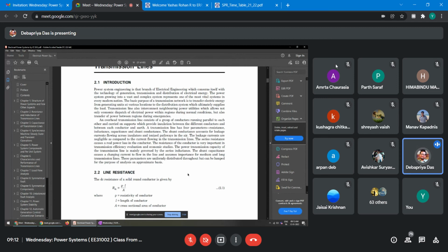When a transmission line is carrying alternating current, you have a magnetic field, therefore you have inductance, right? And certain things are beyond the scope of this course. That is, when a conductor is carrying AC current, the current density across its cross sectional area is different at different points. Later we'll see that. But in that case, it internally links the flux, and externally also it links the flux, because it's carrying AC current. How we are assuming and what we are doing, we will see that.